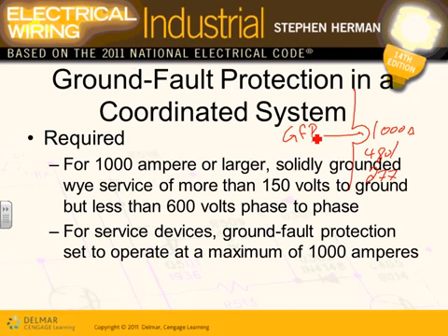The reason that they do it this way, guys, on major electrical equipment, is because if you have 1000 amp 480/277, the ground fault is so high that it could be very destructive, but that cannot be sensed by the circuit breaker. So you could have a 700 amp ground fault sitting on your system, burning your building, and the circuit breaker sitting there doing nothing. So what they do, Karen, is they have a specially designed function or device that can be installed in the circuit breaker or separate, that looks at the current going out of the phases and coming back on the neutral, and if there's a substantial difference between the two, it will trip.